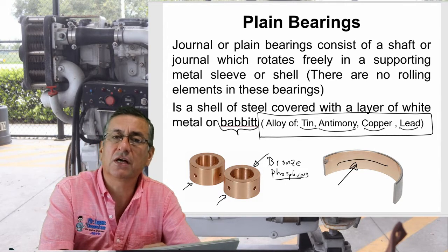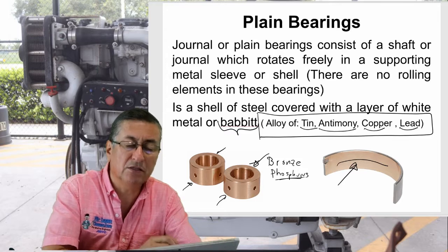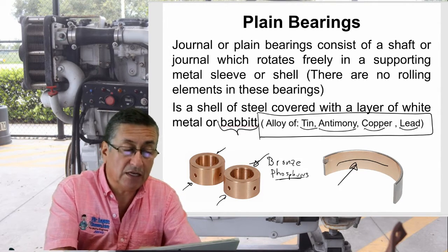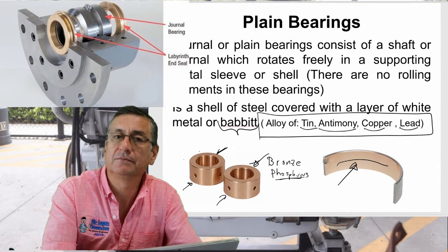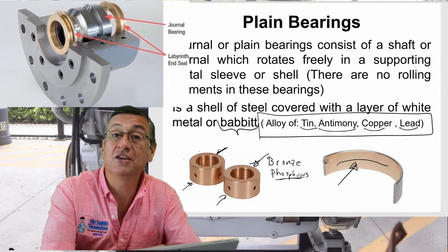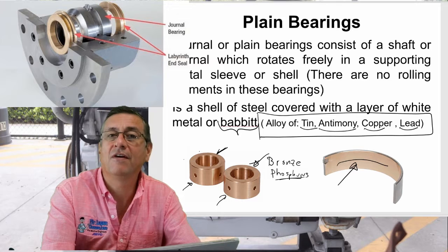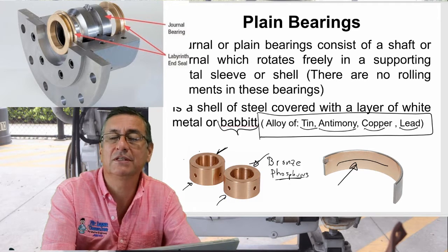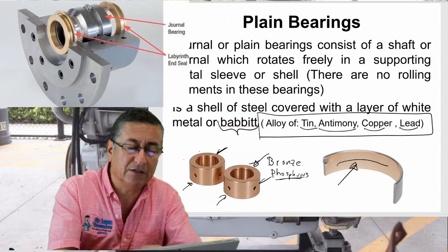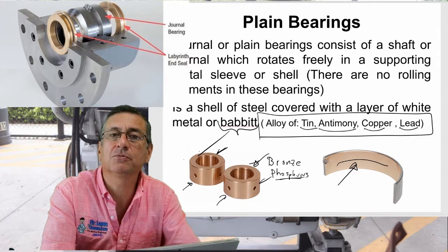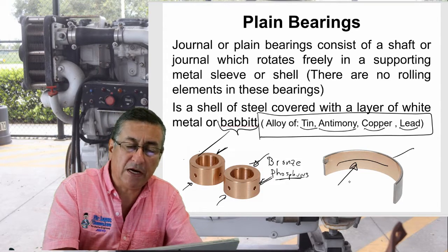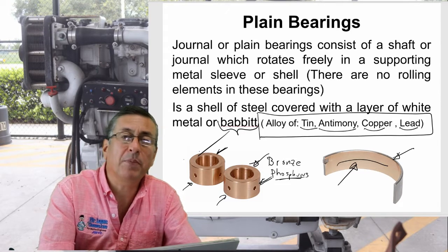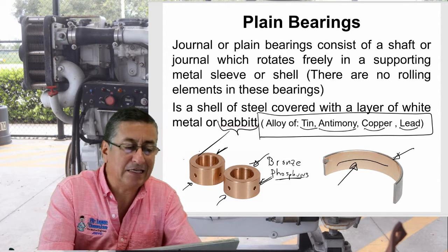The shaft of the starter motor rides in a couple of bearings. Those are bronze bearings. Plain bronze bearings like this are used in the shaft of the turbocharger. The turbocharger is spinning around 150,000 RPM. It's a high speed. For that reason, those bearings are recommended for high speeds. Those bearings are used in turbochargers and in starter motors. And those plain bearings are used in crankshafts, in different types of engines, gas and diesel.